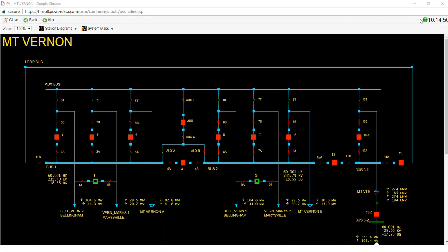In the upper right-hand corner, you'll see the sim time and the status. The sim time should be advancing if I see the green dot. The green dot means the simulator is running. A yellow dot means the simulator is paused, and a red dot means that the simulator is stopped. If the simulator is not in a running state, you won't be able to do anything. It's very common to forget, after you load a base case, for example, to hit start. So just be sure that you do that before you try to take any other actions.